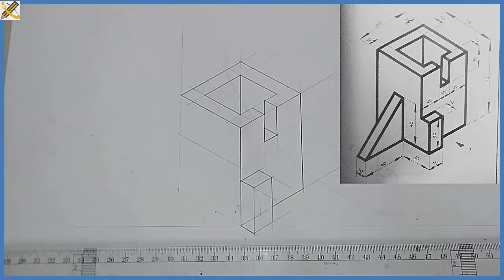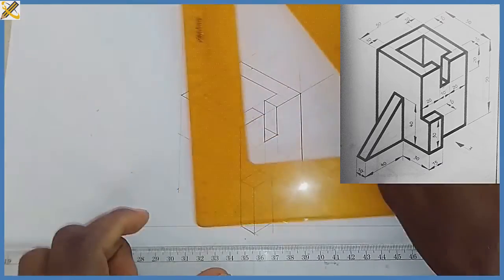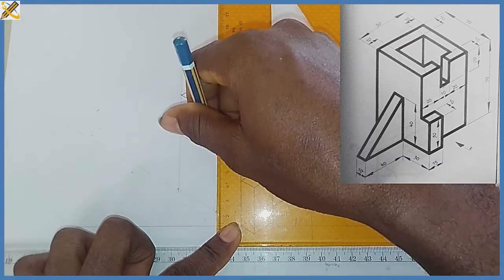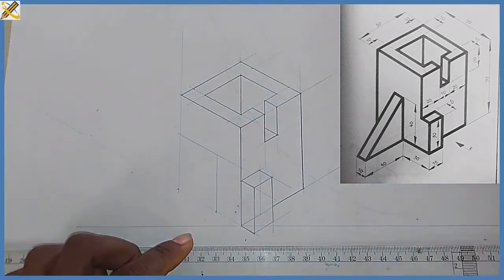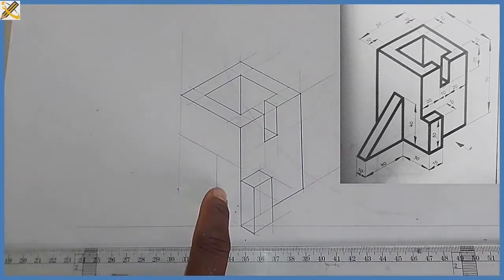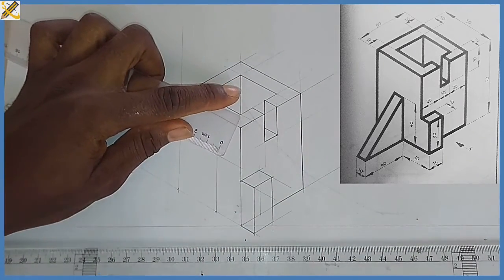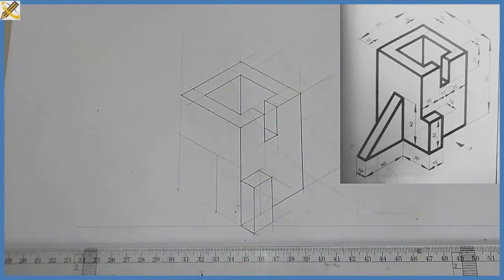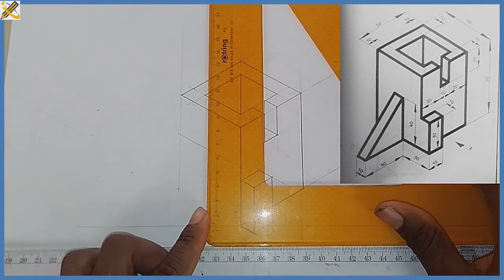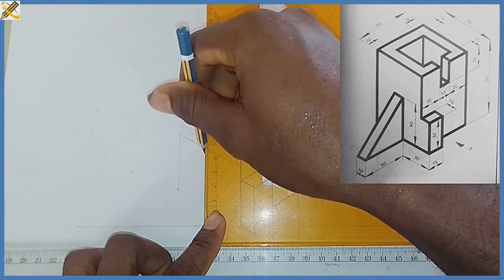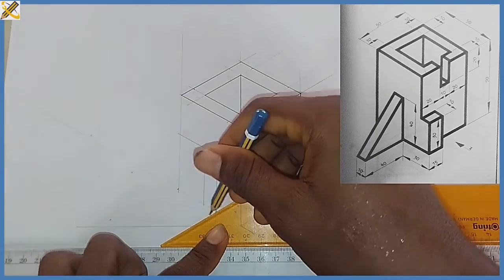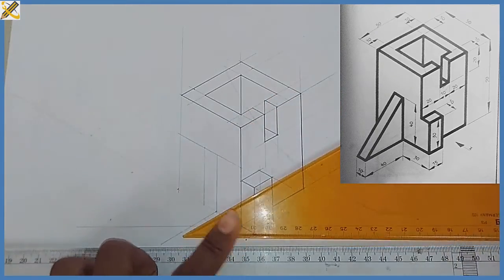So I'm going to pick my set square. All right, then on that mark of 30 right here, project a vertical line upwards. All right, so just follow me. We are told that the thickness of the web right here is 10. Yeah, so picking the thickness of mark of 10 as it is over there. All right, and we are told that that mark of 10 also, I'm going to project it vertically first of all. Then I'm going to draw my extensions. All right, this junction out towards here in this manner.